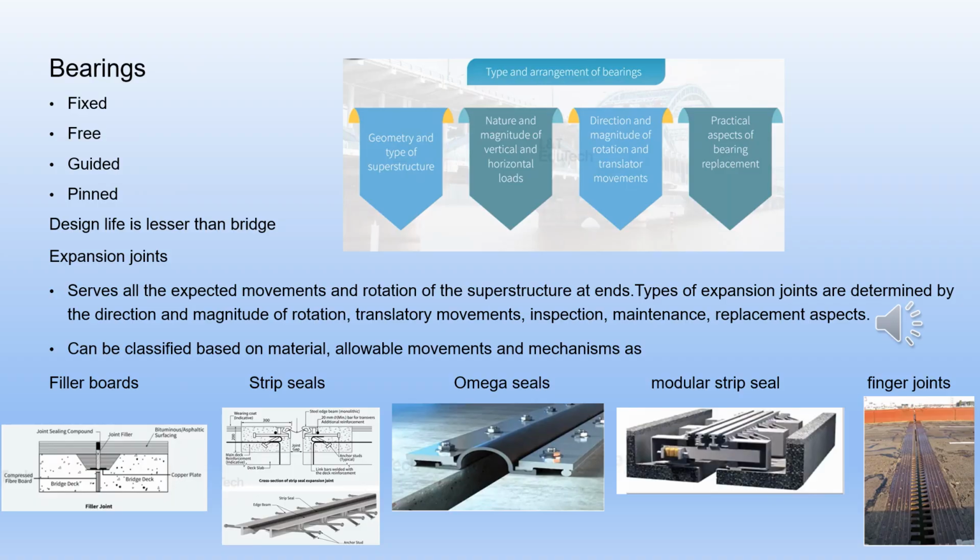Bearings play a major part in the deck articulation, which in turn significantly influences the design. Bearings are classified as fixed, free, guided, pin, etc., based on the nature of movement they allow. Bearings are also classified as elastomeric, PTFE, also known as polytetrafluoroethylene, spherical, metallic, etc.